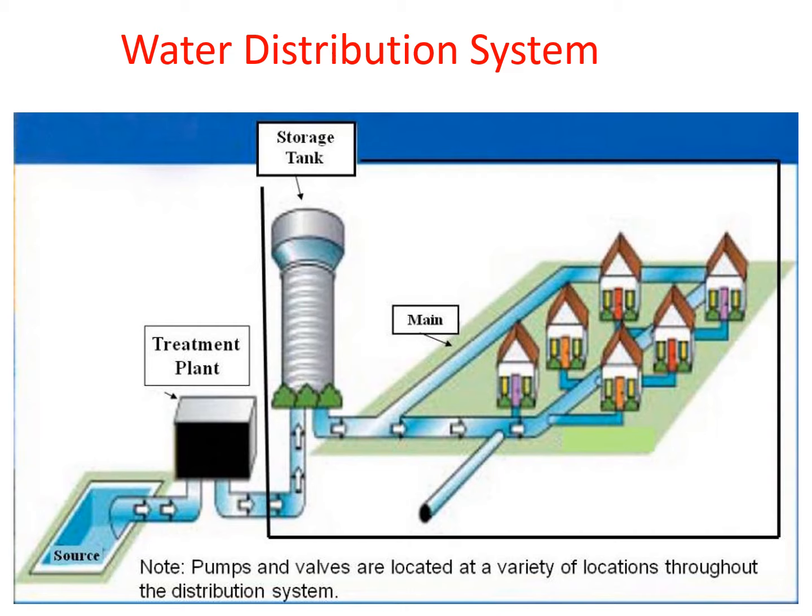After the clear water reservoir in the treatment plant, as I discussed, this water is to be lifted up to the overhead tank, and from this it will come through gravity, and through various pipelines it will reach individual houses, and it will reach your house. And whenever it reaches your house, it has to fulfill all the requirements of the drinking water standard 10500:2012, and the most important parameter is residual chlorine, that is 0.2 milligram per liter is to be maintained. So this way you can prepare the whole flow diagram, and along with that you can write down all the functions in short.